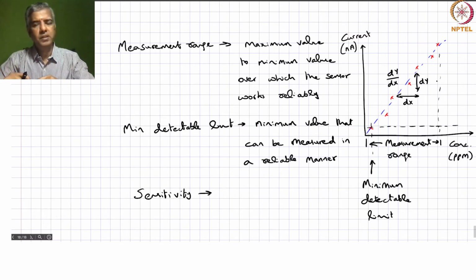So that's actually 10 power 6 units, and what determines the smallest unit you can pick up would correspond to the least significant bit of your ADC. So if it's a 10-bit ADC, then you say 2 power 10 levels you can support. If you're swinging from 0 to 1 volt, then that corresponds to roughly a millivolt. So that's actually corresponding to 30 dB. So from millivolt to a volt you can support, right? So those are some of the considerations that you have.